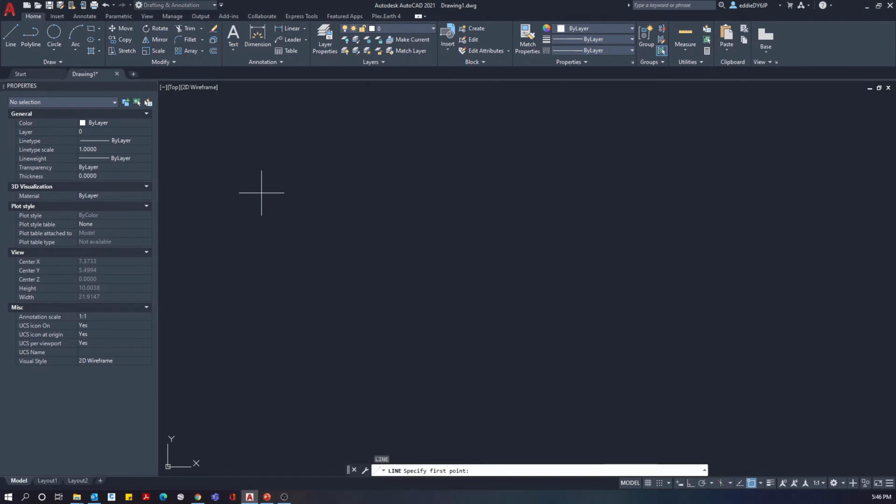Now let's draw a basic line over here in our model space. We can now make another line, and when we come across, we can snap, and you'll see that it automatically gets attracted to that endpoint. On my crosshairs, I now have a green square that lights up to tell us that we're near the endpoint. So if I click, now that is attached at that point.